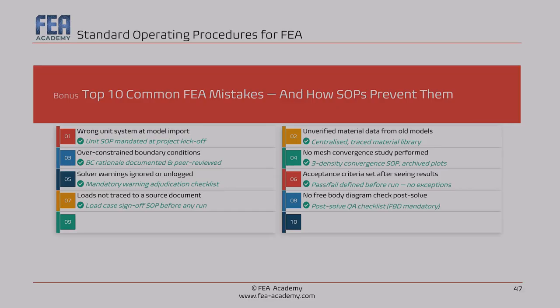The eighth error is no free body diagram check post-solve. The free body diagram check takes 15 minutes and catches a significant portion of the major model errors. Okay, because it is by nature the best check to verify the load path. Skipping it to save time is a false economy. Make it mandatory.